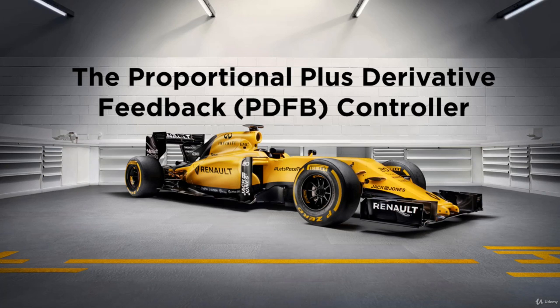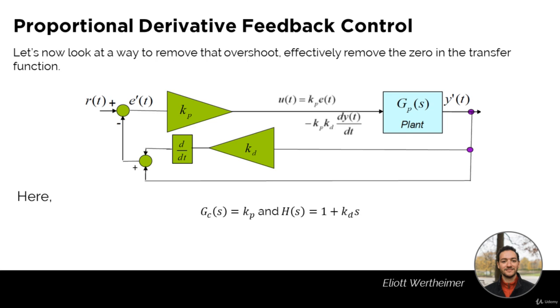Hi guys, in this lecture we will look into the proportional plus derivative feedback controller. Essentially, it's a proportional plus derivative controller with a slight tweak that allows us to obtain great improvements. Proportional derivative feedback control allows us to remove the overshoot that we saw in the last lecture. Effectively, it removes the zero from the transfer function.